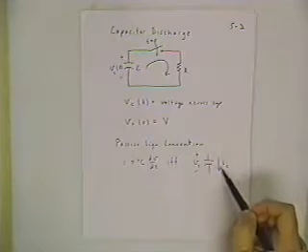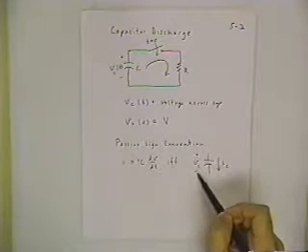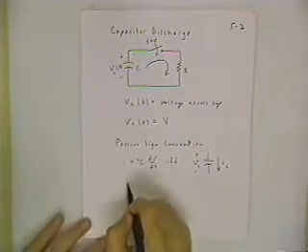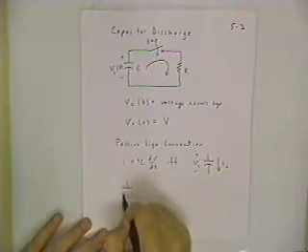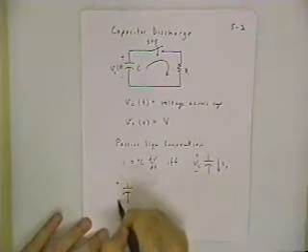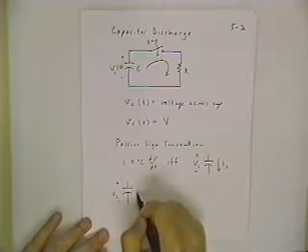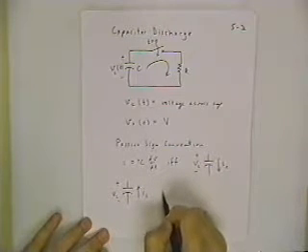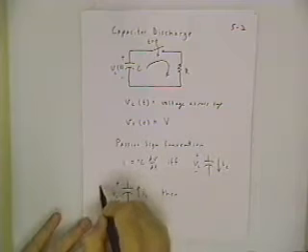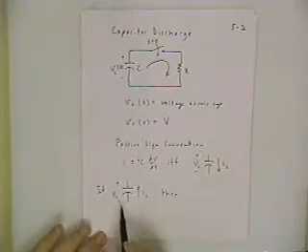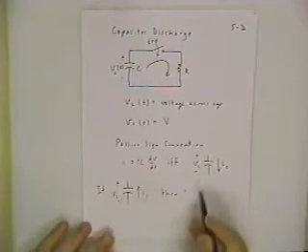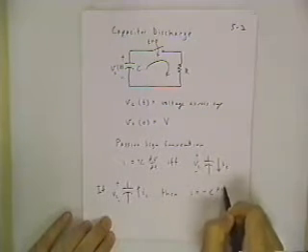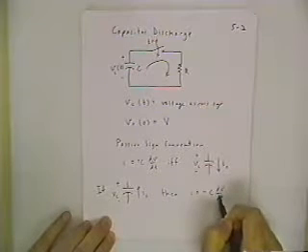So if your capacitor current is flowing from higher to lower potential, then you can write this equation. What happens, as in our present case, is the capacitor has a voltage with this polarity, and the current's actually going in the opposite direction. So let's make this a good if-then statement. If this is the situation, then the linear model reads I is equal to negative C dV/dt.